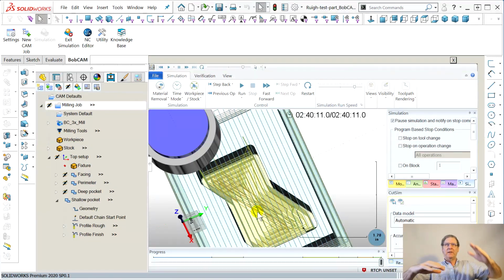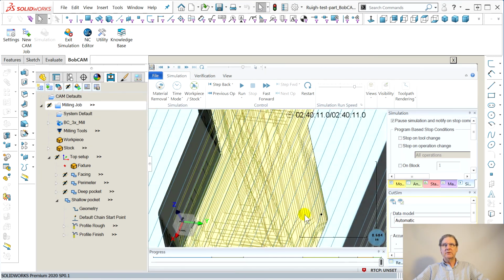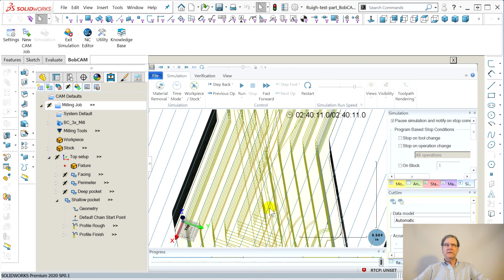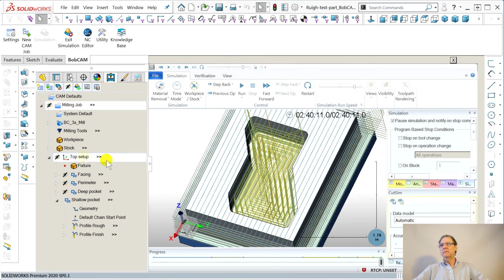You can kind of see when you tell it, hey, I want 6 passes, it starts folding things over on itself, saying, well, you wanted 6, I want to give you 6 no matter what I have to do. And that's what generated that toolpath that got into the edge. Apparently 5 is enough, because it looks like it's cutting all the material out in the center part. Why it's a different shape than the deeper pocket, I don't know. Plunging, all that stuff, I guess we're okay.